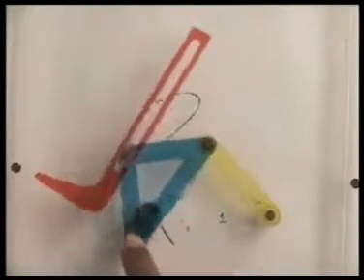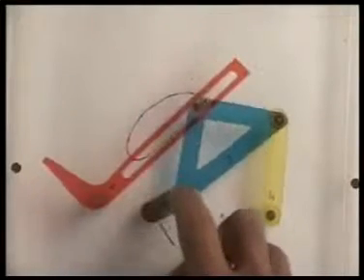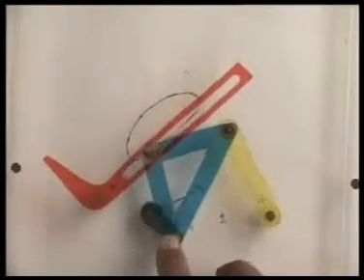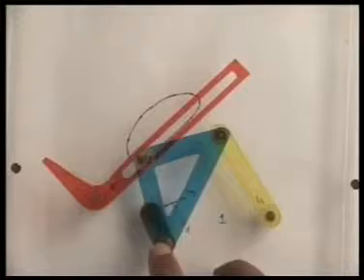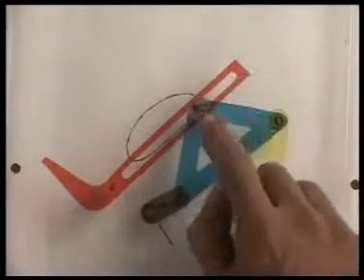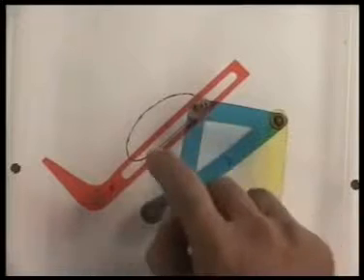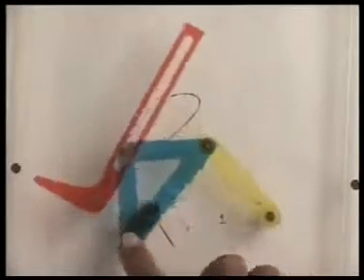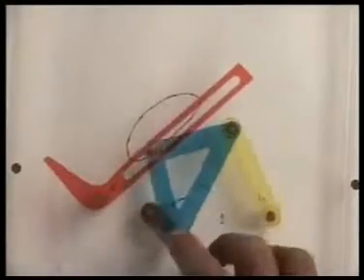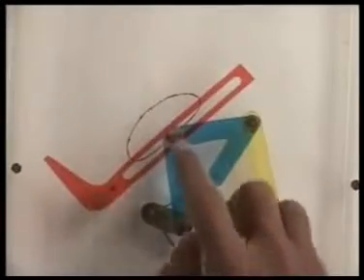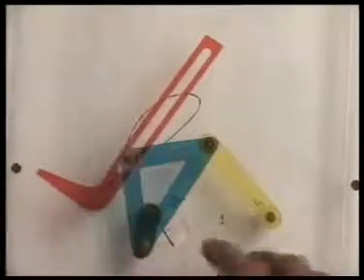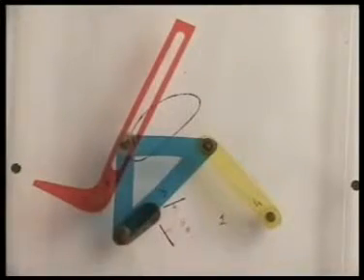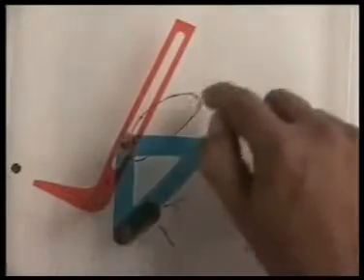As we give continuous input rotation to this crank rocker linkage, we should notice that during this interval of the rotation of the crank, the output link hardly moves, because this coupler point goes along a fairly good approximation of a straight line. And as soon as it comes out of the straight line portion, the output link starts moving, and this is the extreme position of the output link, when this line becomes tangent to this coupler curve.